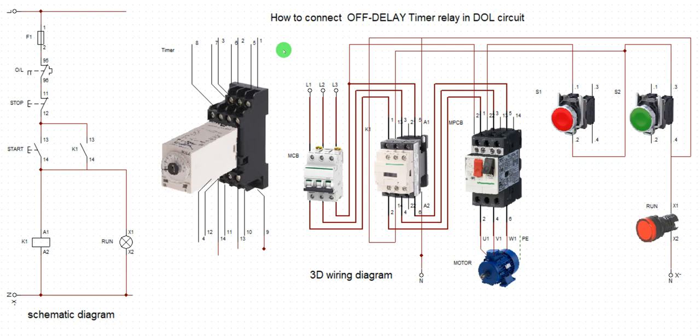The on delay timer can also be used, but the disadvantage of using it is this: when the task is completed and the equipment shuts down after the time has elapsed, the relay will still remain energized. It will execute the function and shut down the operation at the time it is calibrated to do that, but the power signal to the relay will still remain there. So supposing you are using a DC signal for the operation, the battery will still be drawing power. The power to that battery will still be consumed after shutting down, because of the configuration.